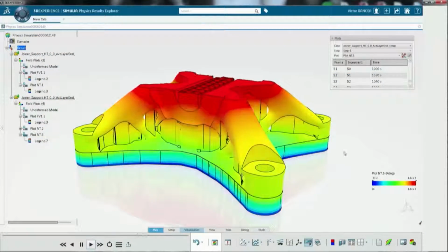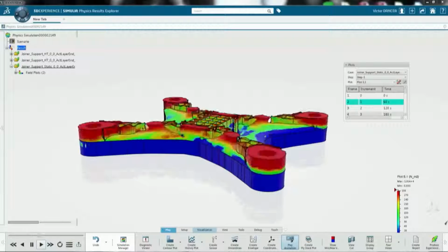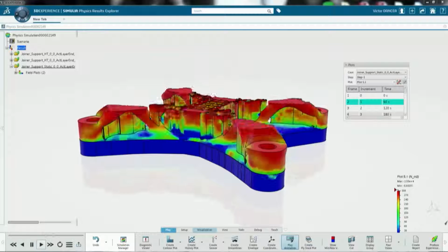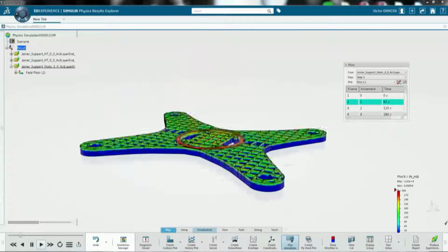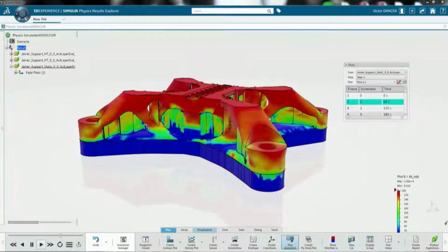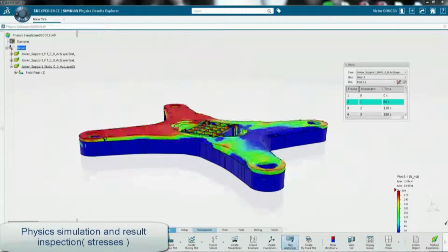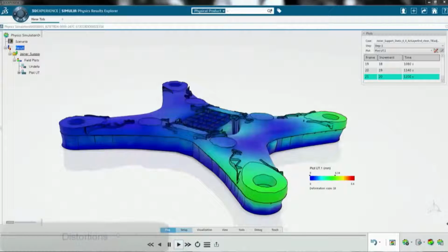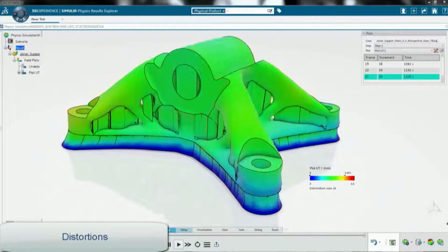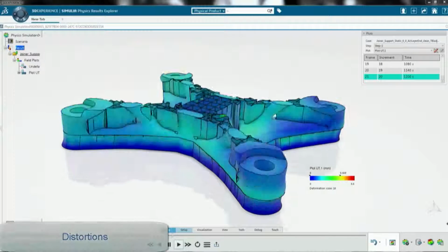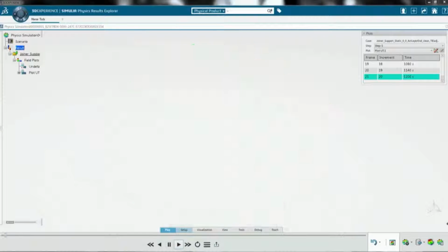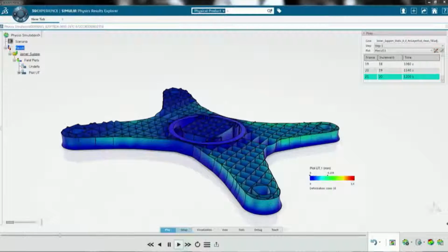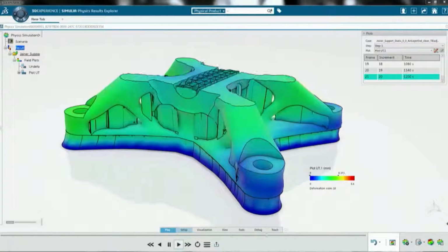You obtain contour plots like this of temperature gradients as the part is being printed. So now, basically you have the laser inputting heat into the system, and you have the cooling and convection and radiation that happens continuously and compete with each other, leading to these rapid thermal gradients. In the end, what you get is a deform plot or distortion plot as shown here, and you can see that even with this simple application that we did here, we get about 0.5 millimeter max distortion in the part.